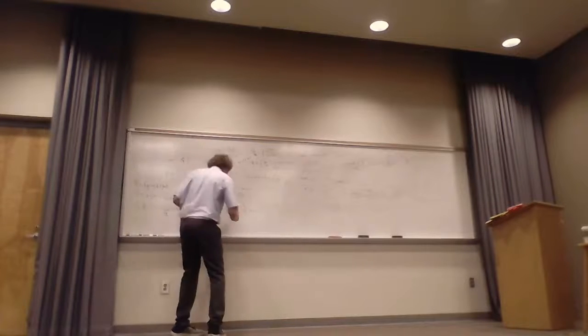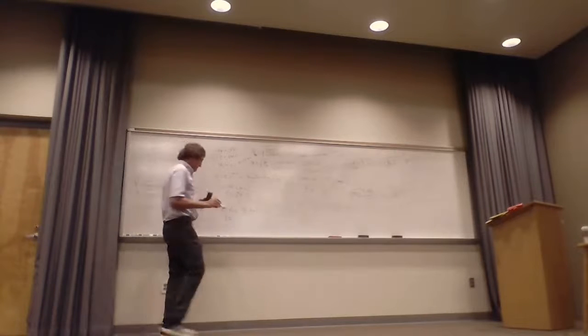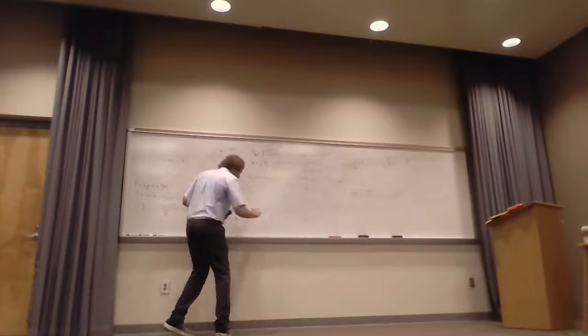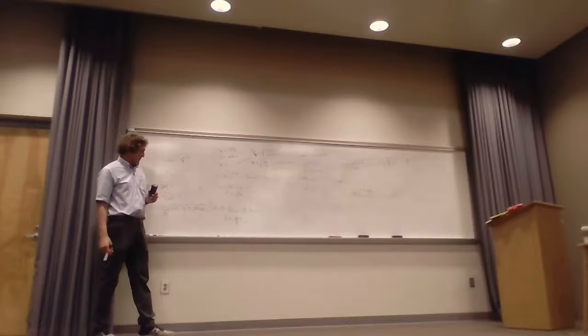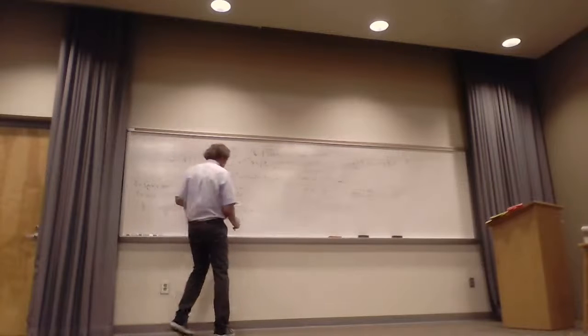How do you always get wavelength? Don't put C over F. That's wrong. How do you get wavelength? People do that. It's 2 pi over beta. Very good. So 2 pi over beta, and what's that going to be? 2 pi over 4,000. So 4 times 10 to the negative 3. Say again. 1.41 times 10 to the negative 3.